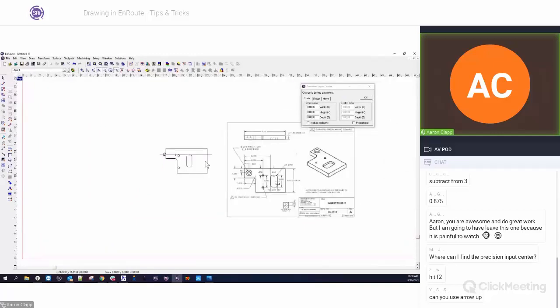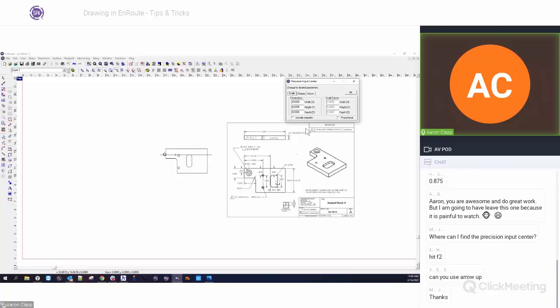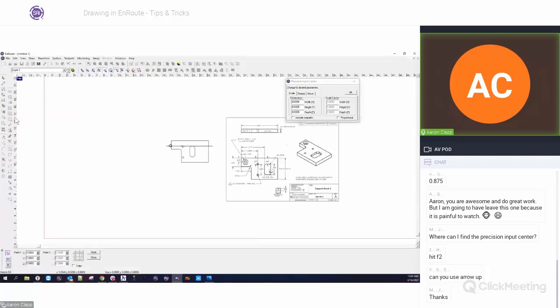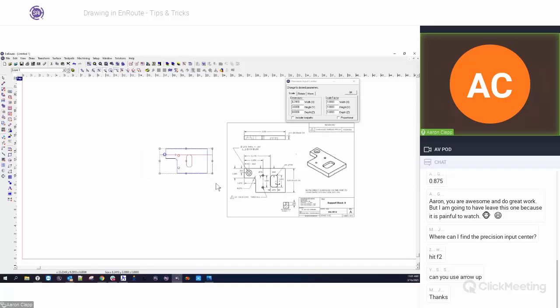Another thing to consider also is symmetry. If you have a drawing that's symmetrical on both sides, you only have to draw half of the file, and then you can mirror your job using the mirror tools. If we go in here and grab our mirror tool, I can mirror flip horizontally or vertically, or I can mirror it based on a line. So I can generate half of it, and then flip it to save myself some time, mirror it across and make a copy of it so I get double. That's another really good tool to know that's available.